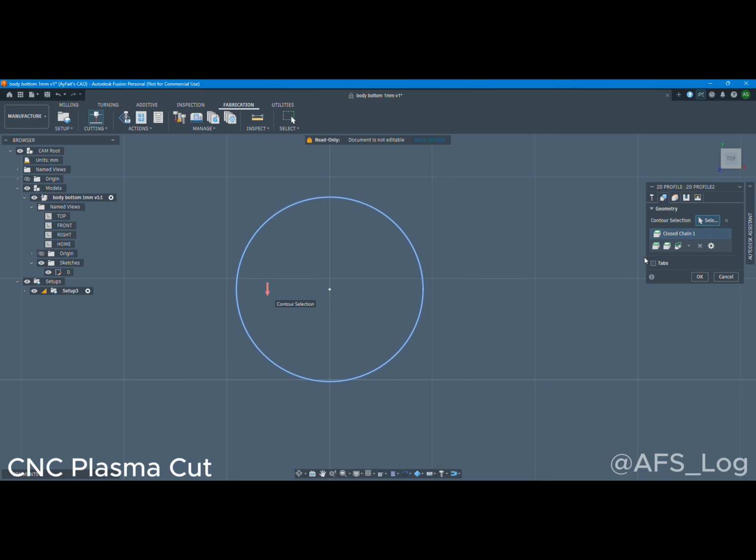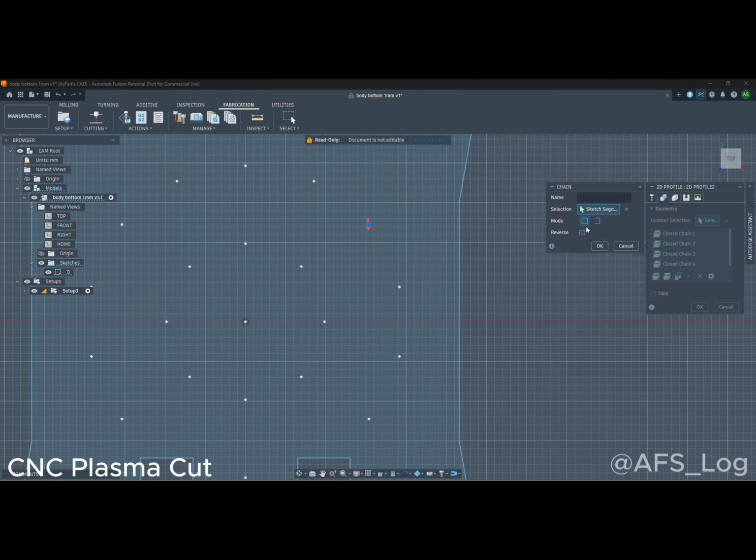So we go on like that, and we go on to select everything. Now it's inside. Again, let's see, it's inside. Good. Now there are times whereby you're selecting your geometries and you click on the internal geometry or any geometry twice. This is what happens when you do that. This chain dialog box pops out. Now what you need to do is just to click on cancel.